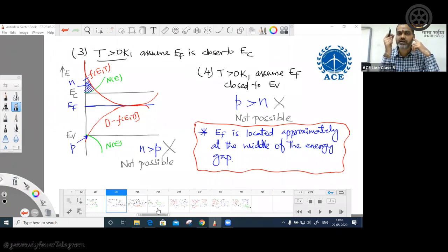These points we will discuss when we cover optoelectronic devices, where there are three different transitions: energy less than the energy gap, exactly the energy gap, and more than the energy gap. With less than the energy gap, it can move to a certain level, but it cannot find any energy level, so it comes back. With exactly the gap energy, it reaches the conduction band edge. If you give higher energy, it can move into a higher energy level in the conduction band. Got it? Yes, sir. Thank you, sir.